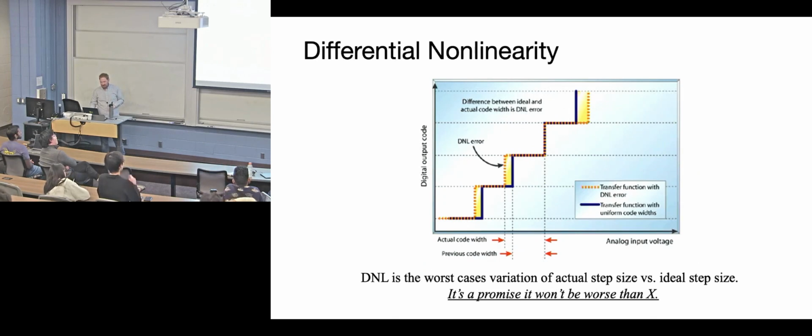But the ones that you can't really deal with are differential error or nonlinearity, where there's some aspect of your outputs where the spacing is not all the same. And where this really comes up is when you're making a control loop and you're trying to servo one analog value to some value with a digital value, but the digital may overlap. There may be problems. You might be doing a search and actually get caught at a local minimum. That can actually happen because there are so many bits that there are little bits of error.